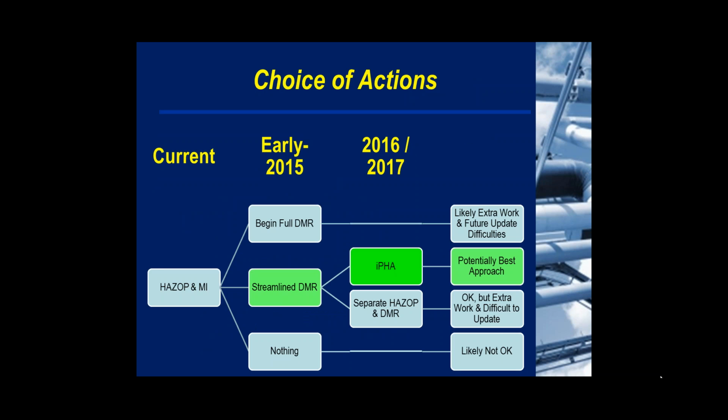Mechanical and metallurgical failure mechanisms include loss of thickness issues like corrosion under insulation (CUI), sulfidation corrosion, of course, chloride stress corrosion cracking, hydrogen embrittlement, other types of corrosion and cracking mechanisms, and also high temperature hydrogen attack. These are well defined in API recommended practice 571, and there are some guidelines. If you don't understand these, 571 provides a lot of background information to get on top of these items.